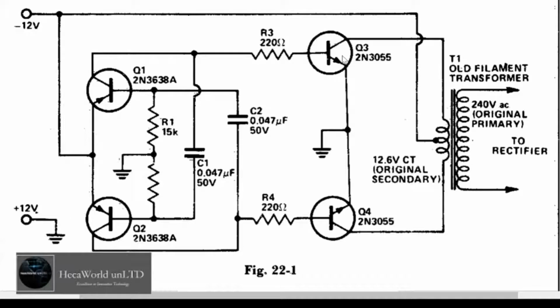Let's say you use a 2N2222, for instance. The base to emitter reading for that transistor will be around, let's say, 617. But the base to collector reading will be around 615 or less. The emitter reading will always be slightly higher than the collector reading. So you put that in your pocket, and you keep coming.